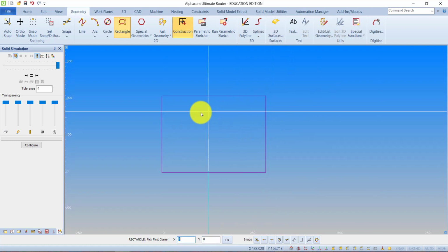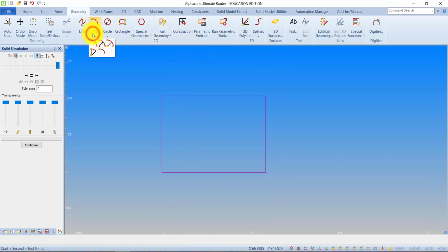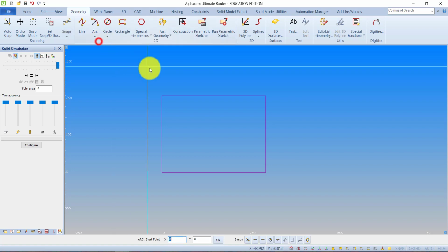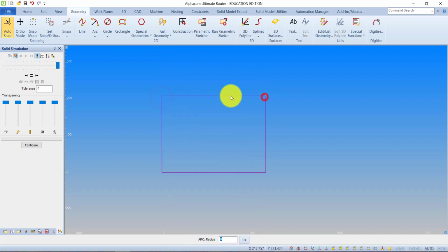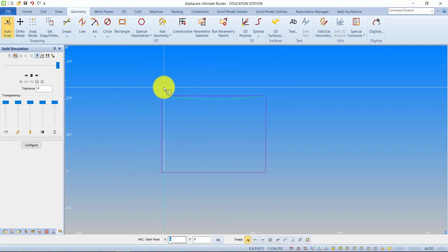That's just going to be the frame of it, but I want curved edges. So turn off construction and let's go to arc, and I want this second option, which is 2 points plus the radius. So I'm going to pick up the corners with the snap tool. So turn on the snap tool. Left corner, right corner, and the radius is going to be 1200, and it's gone the wrong way, it's gone down the way. So instead of starting and clicking the left then the right, I'll just press undo. This time I'm going to pick the right then the left, so right and left, 1200, OK.